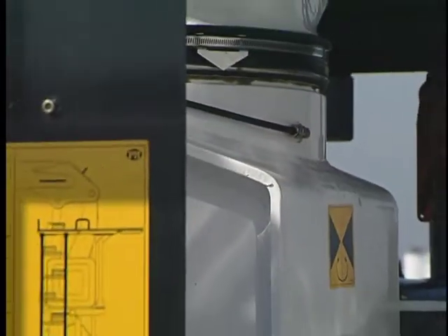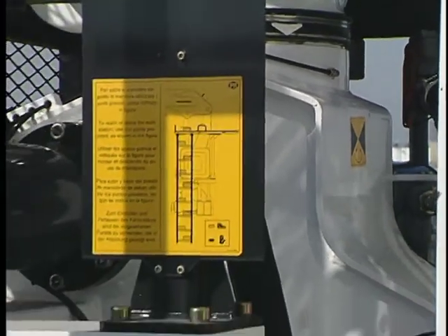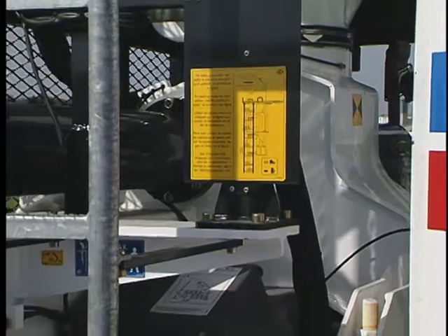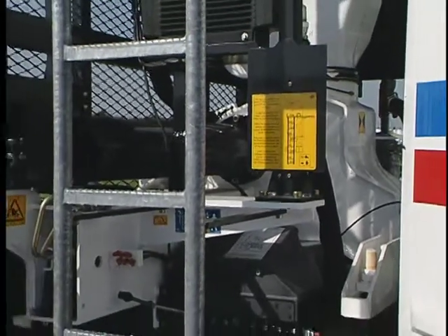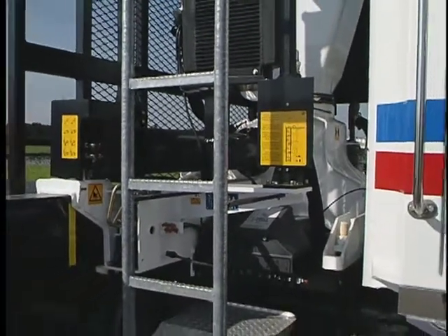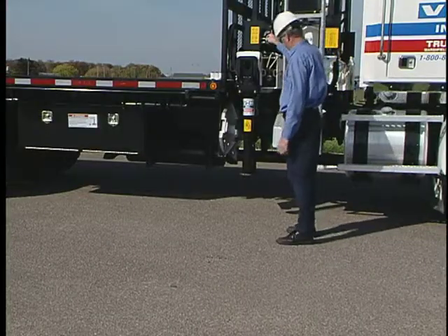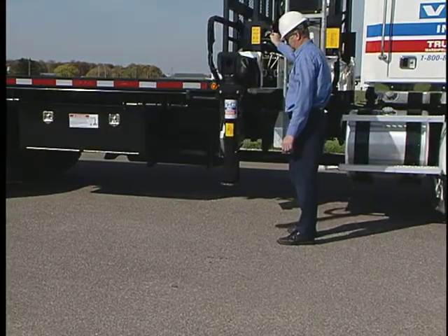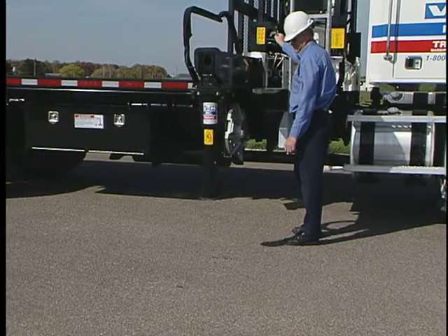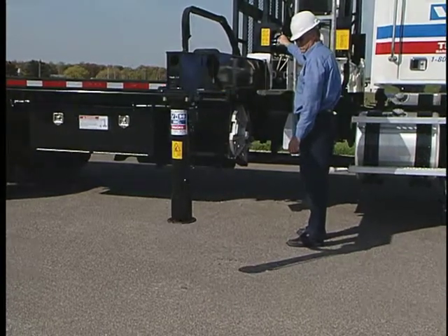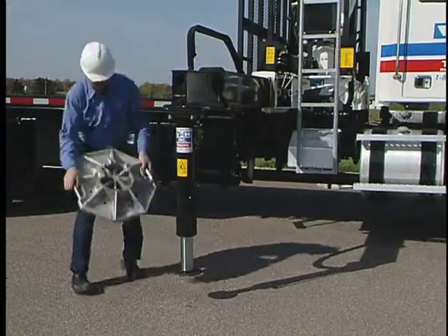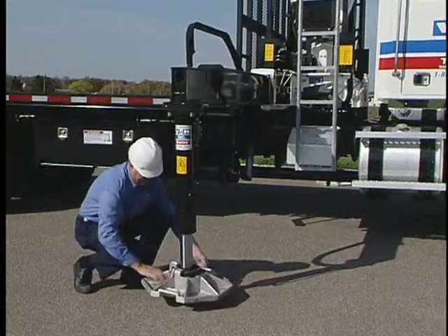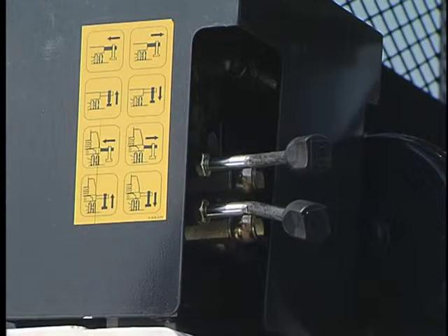The crane base is a fabricated high-strength assembly and is the fastening point to the truck chassis. Hydraulic, extendable outriggers reduce total setup time, ensure ease of use, and provide leveling and balance during operation. Outrigger controls on most models are located independently at each outrigger to provide line-of-sight activation.